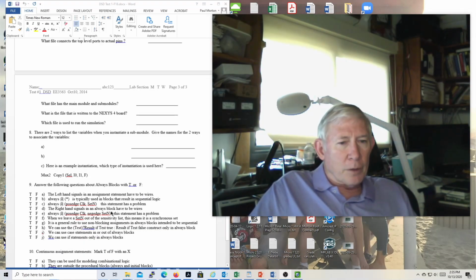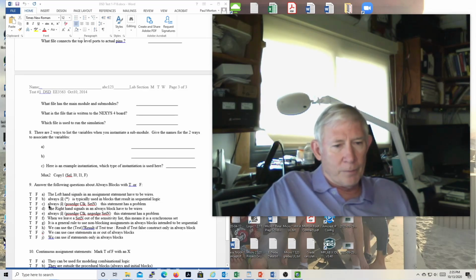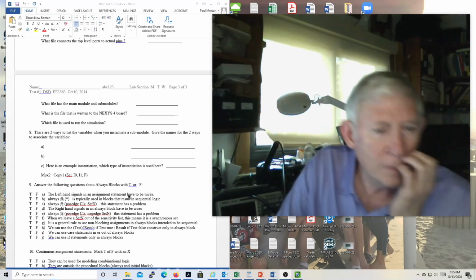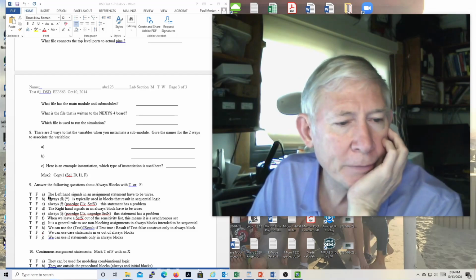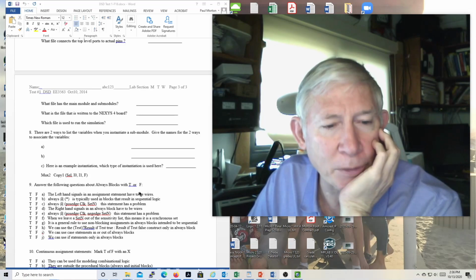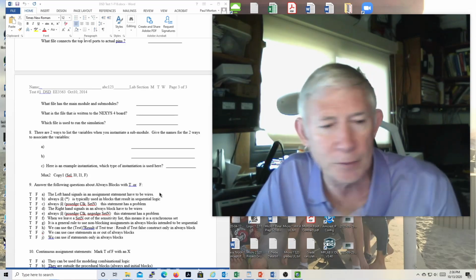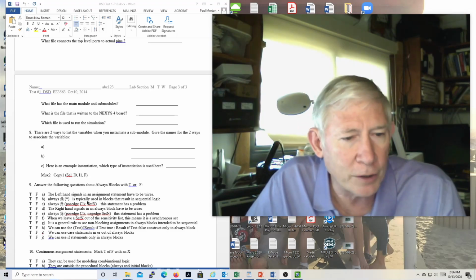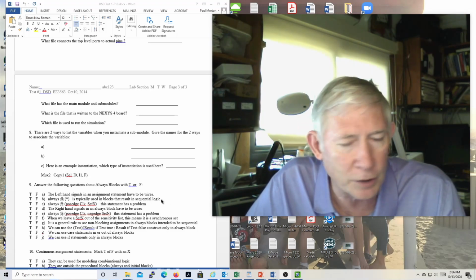Okay, answer the following about always blocks. The left-hand signals in an assign statement have to be wires. No, that's... oh, yeah. Well... Okay, bad question. If it's inside an always block, they have to be registers. But if it's outside an always block, they have to be wires. Okay, the always at star is typically used in blocks that result in sequential logic. No, they typically use them in blocks that result in combinational logic.